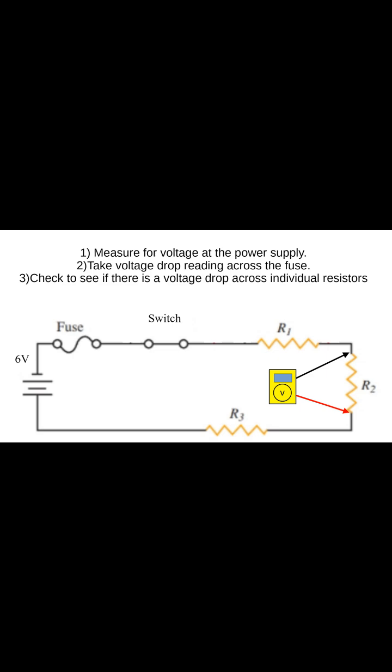If that bulb was open, the voltage drop across that bulb would read the battery voltage. In this type of circuit, there's only one path for current to flow, so no bulbs will light if you have an open in the circuit. See figure 5.4 again.